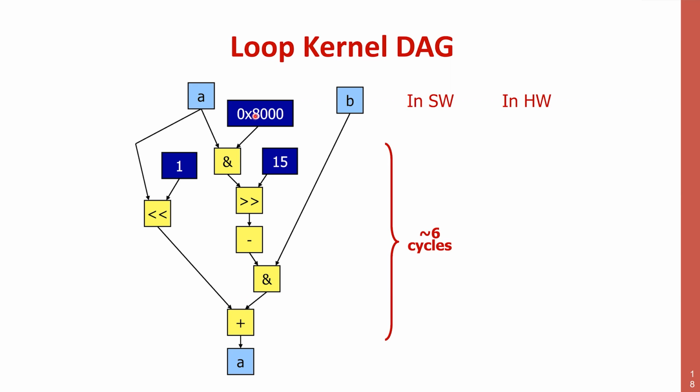So what is the result if I AND the 15th bit of A with 1? The result is the value of the 15th bit of A. So do I need transistors for that? No, I need only to connect this bit here. So you see what happens. There are 0 transistors to do this.